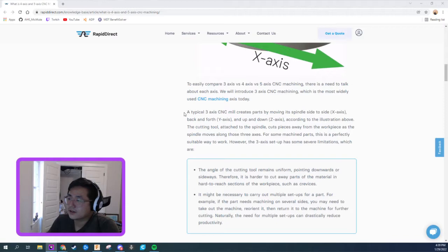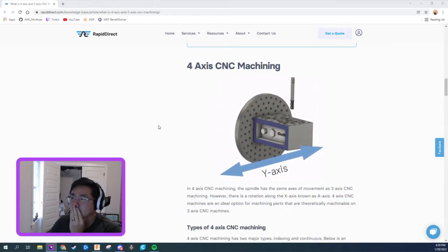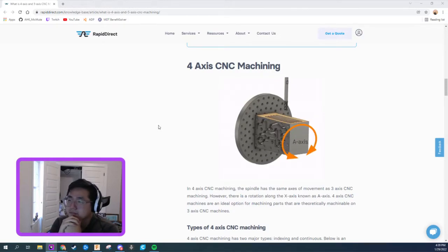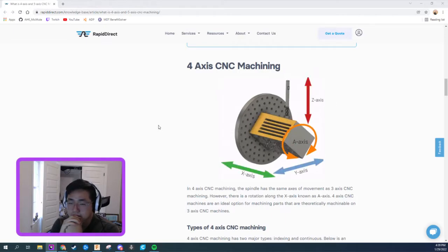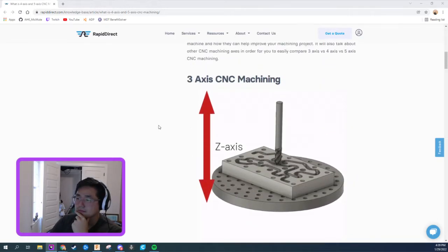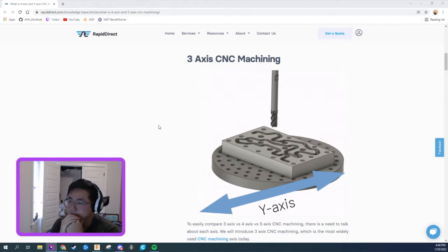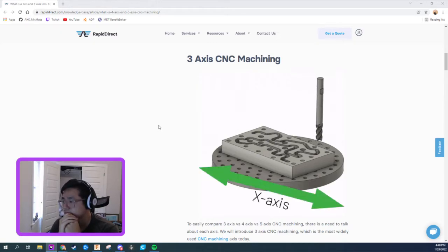And one thought: if they don't have some of the capabilities that you need, specific to the machining environment, there are sort of brute force methods. Like if a feature isn't dovetailing with the 3 axes they have or the 4 axes they have, oftentimes they can sculpture mill or 3D mill or form mill a feature, but that's hugely expensive and time consuming on the machine as well as cost.